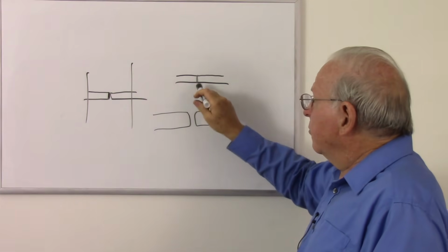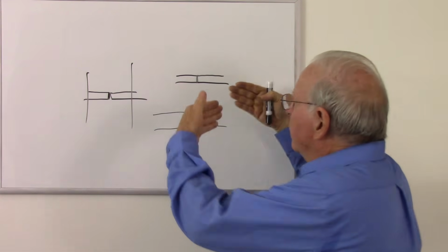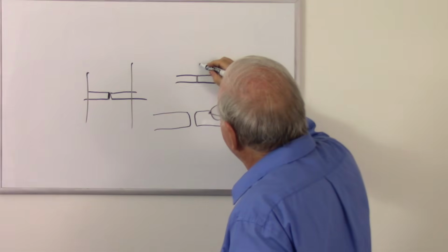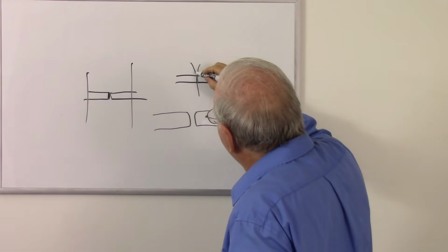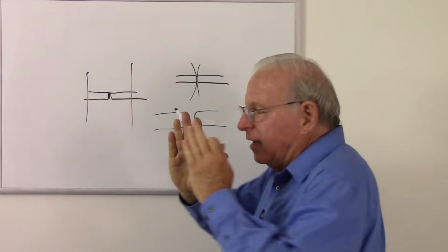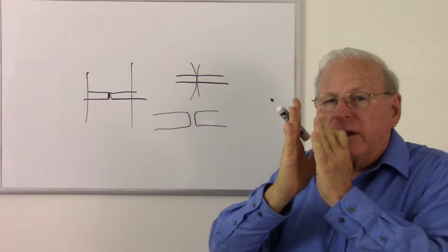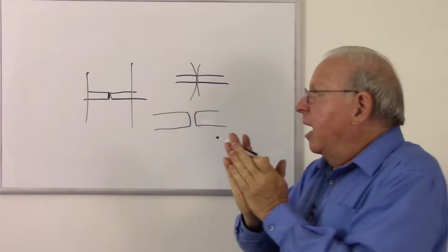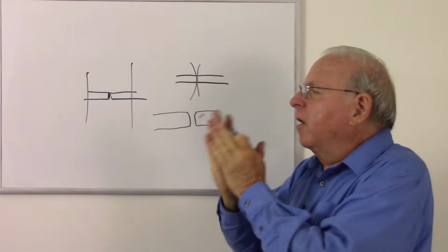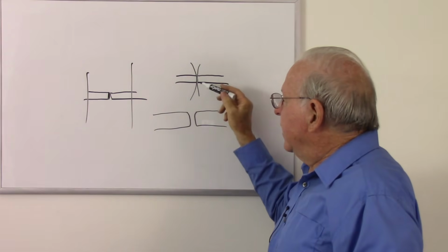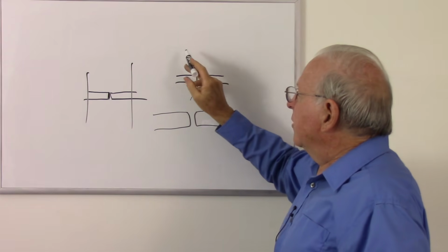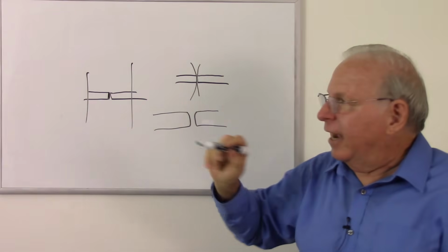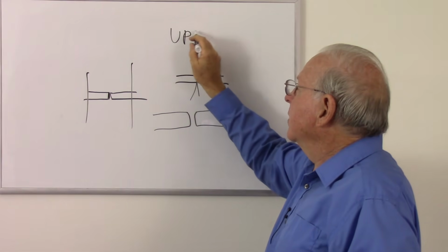Well, that's basically what they're trying to do with fiber optics, is get those two fibers in optical contact, and so they have just the right curve on that ferrule to get those two pieces of glass to come together, and the force flattens them out, and they go into optical contact if you have a really good polish on them. And so that's the idea, to get that optical contact, and that's called ultra physical contact, or UPC.